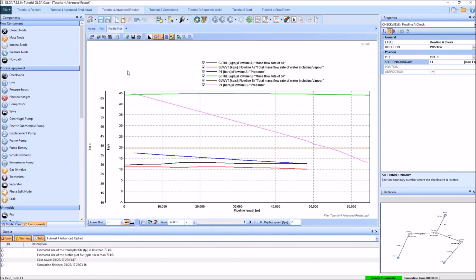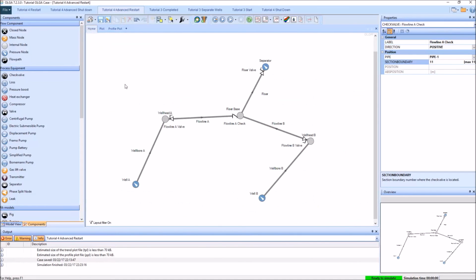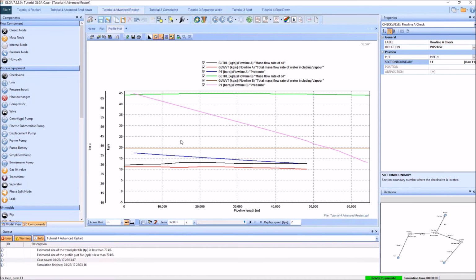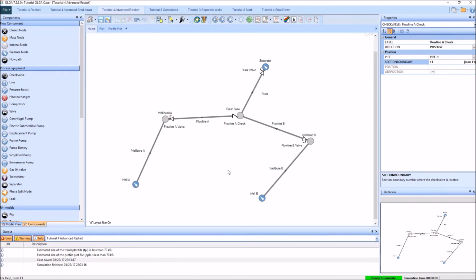So this is interesting because it illustrates that despite the fact that we can get some sort of steady state result out of OLGA quite easily, it's not necessarily that simple to get there from a real shut-in condition. And in order to actually achieve that final expected steady state condition, we've had to go ahead and make a few interesting modifications to our system.